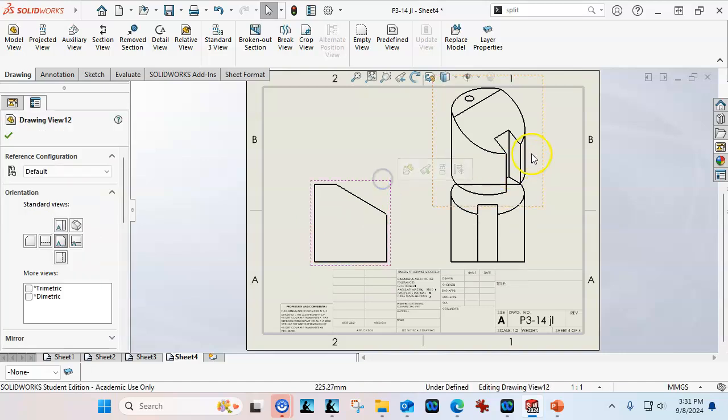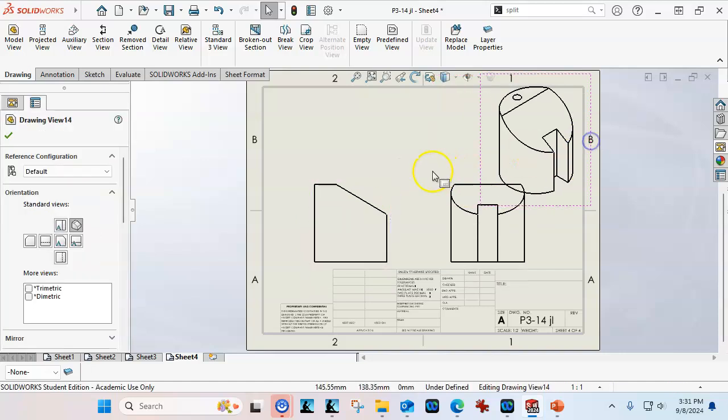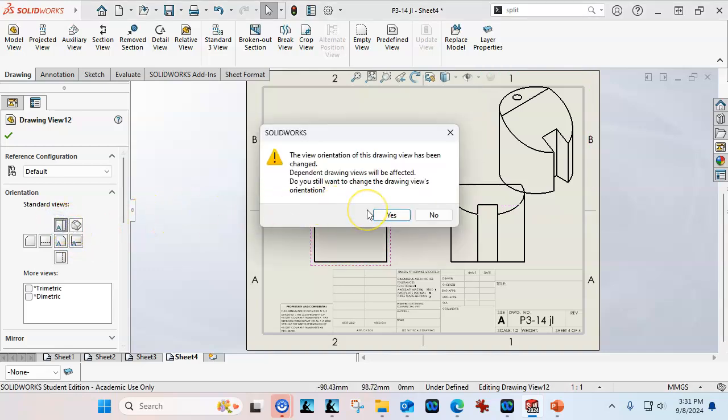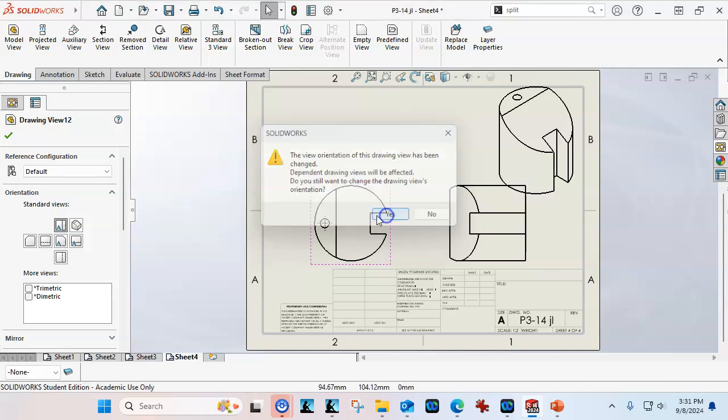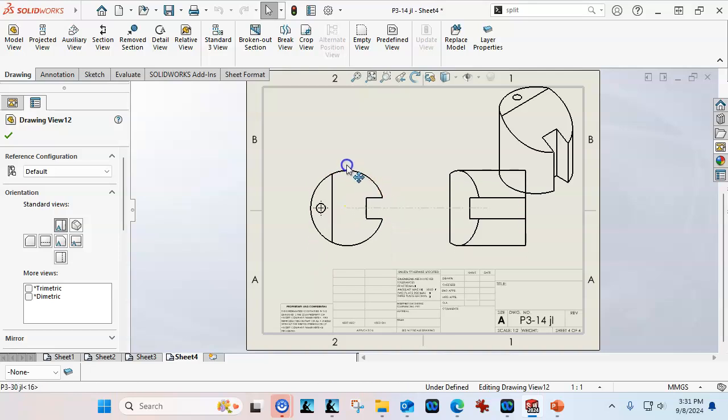I can see that this would probably be better. Let's see, height-wise. Well, let's see if I change it over to the top, then here's where it warns you that if you've added dimensions, and I've done completely detailed drawings and realized that I need to shift one of these views, it deletes the dimensions when it does that.